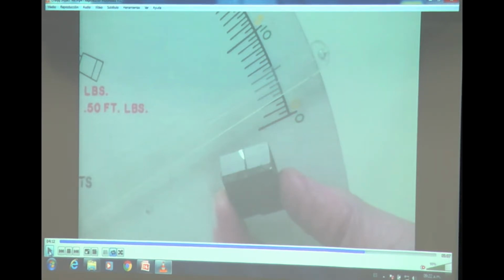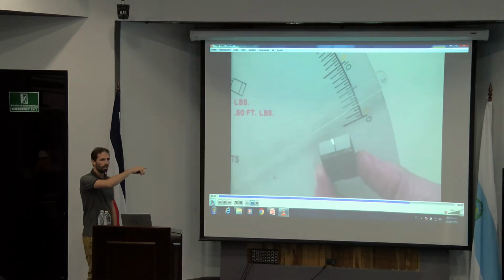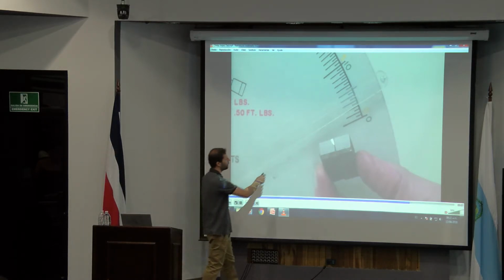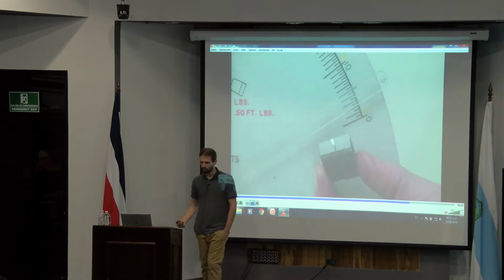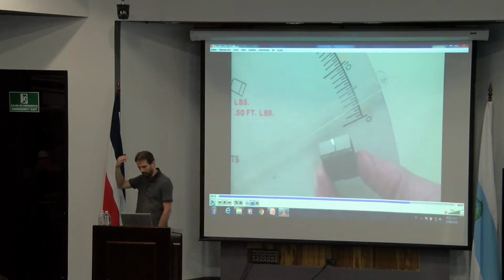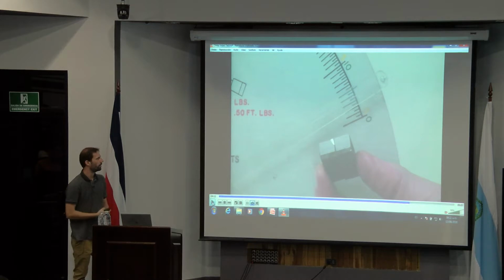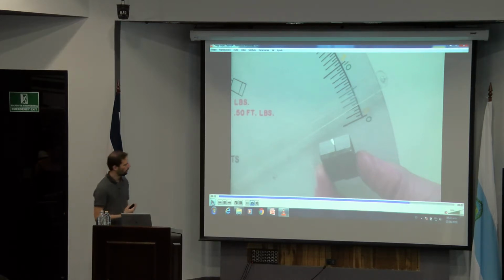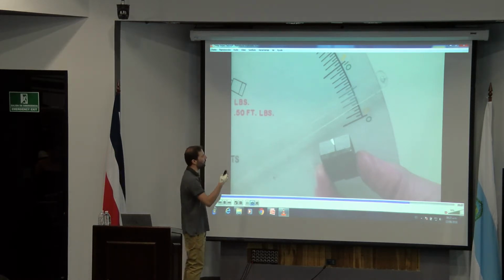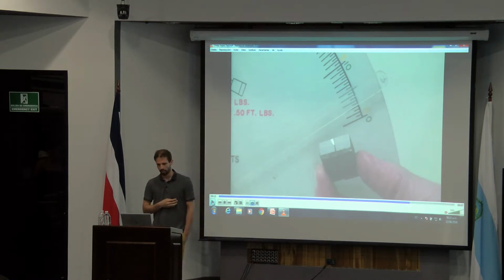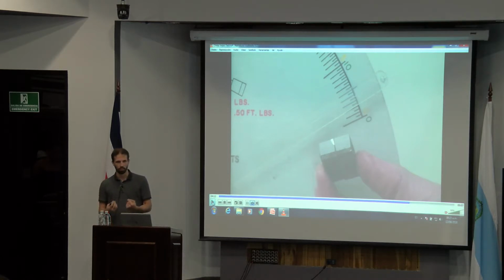So a real reduction of the energy, and the energy, as we had last week, was defined by the potential energy we had in the starting point minus the point of return where the hammer goes back. And so as you can see here, due to this, the hammer was going really high. Due to this, we have here just a low fracture toughness in the Charpy test, or Charpy test fracture toughness.